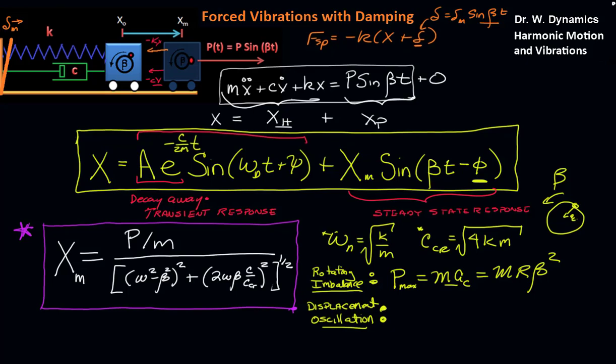And if we drag that through, we'll get the same basic solution set. And that deflection can be converted into an effective force. So P max will be k times deflection max for the system.